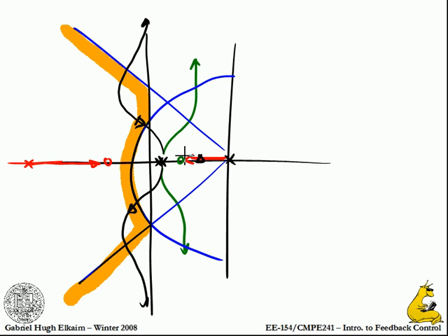All right? So therefore, the pole being in the proximity of the 0 has the effect of essentially, because if they were right on top of each other, the pole and the 0 would cancel, and you wouldn't see anything of the response. So it has the effect of attenuating that response. So it'll be there. There'll be a slow e to the minus at mode in the system, and you won't be able to get rid of that.